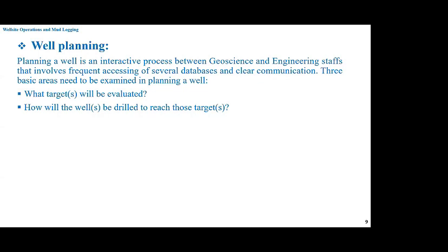Then how will the well be drilled to reach those targets, including the game plan, which includes drilling parameters, drilling fluid properties, also the different sections of the well, intermediate section and main hole section, and so on. Also, how will the target zones be evaluated, including the sampling program in the mud logging and the wireline logging program in details.